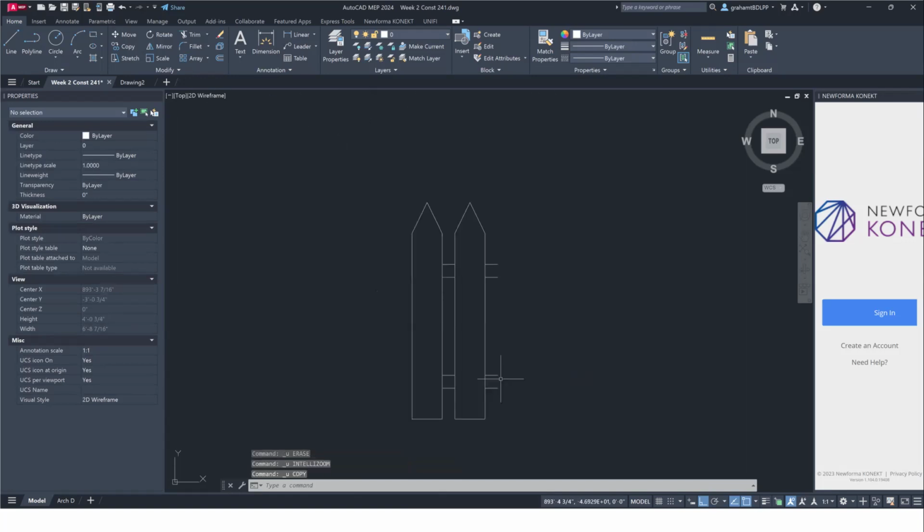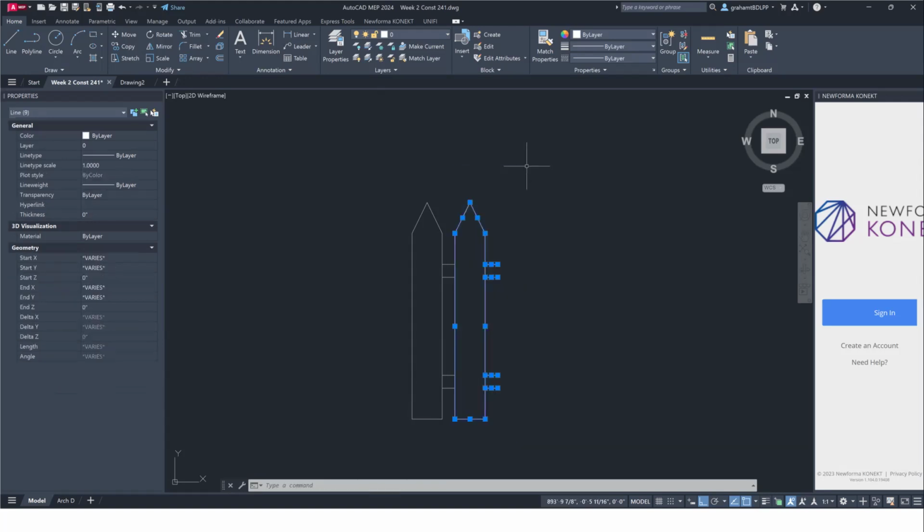So we now have 2, right? We copied 1 over. We knew that it was 8.5 inches away. It was a pretty easy thing to do. The reason we couldn't do this the first time is we didn't have a secondary point for us to grab. We could try to grab off of here and copy to the edge of that, but it gets really tricky. But now since we've got a base point here, I can take my second one and copy from my first location to my second location.